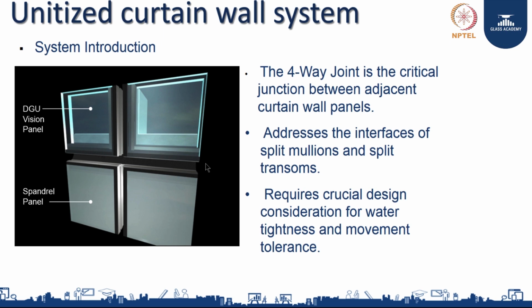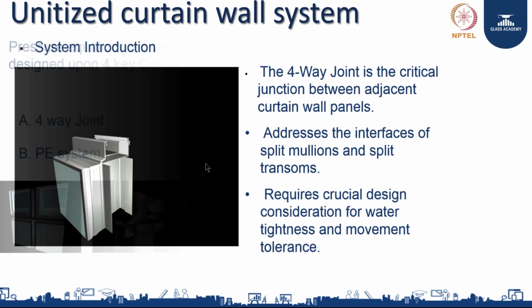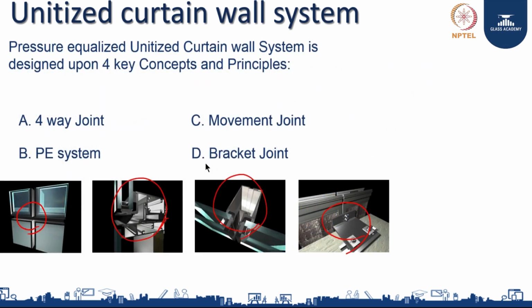So, understanding a unitized wall, it is as simple as you are building a wall, unitizing it in a factory environment. So, it is like manufacturing a furniture, you loose furniture. What they do, they manufacture the furniture in the factory, they assemble it at site. I mean, they put a few screws, then you have a furniture. But in this case, the same, you make a full panel like what you see in the building.